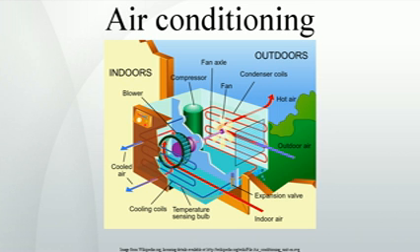Health issues. Air conditioning systems can promote the growth and spread of microorganisms, such as Legionella pneumophila, the infectious agent responsible for Legionnaire's disease, or thermophilic actinomycetes. However, this is only prevalent in poorly maintained water cooling towers. As long as the cooling tower is kept clean, usually by means of a chlorine treatment, these health hazards can be avoided.